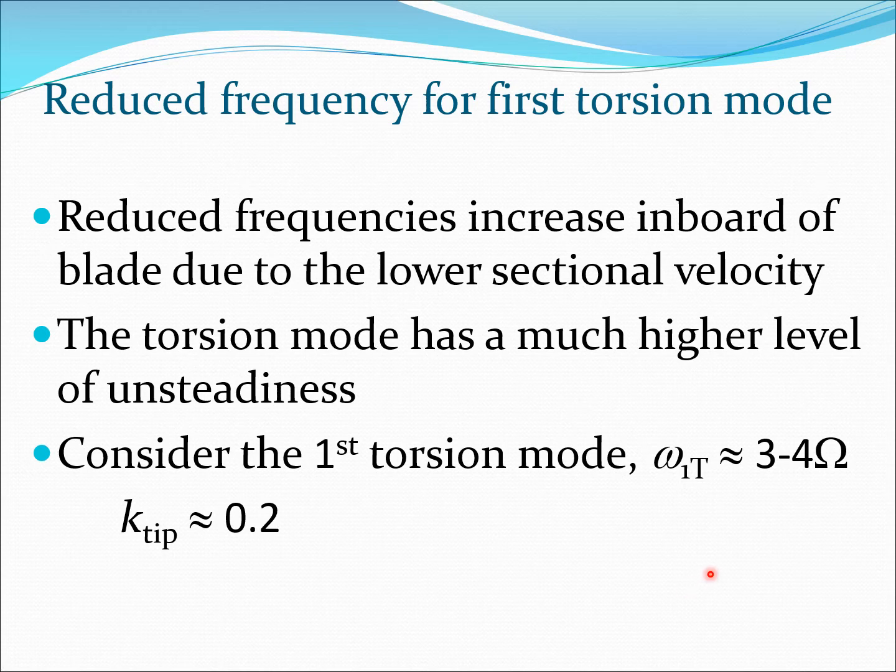So one more thing to realize is that the reduced frequencies will go up as you go inboard of the blade because the sectional velocities will become lower, and that will come out from the formula. Remember that velocity is in the denominator, not in the numerator.